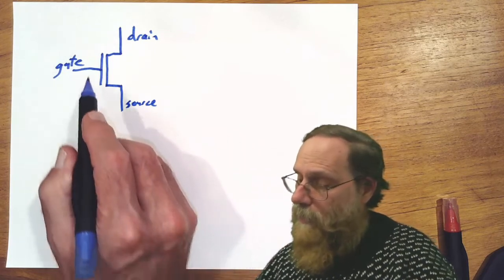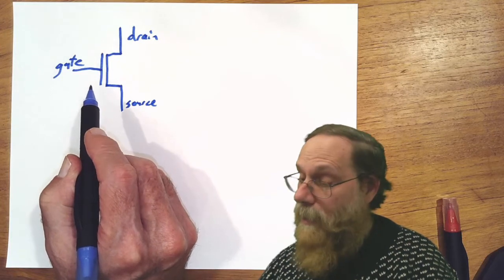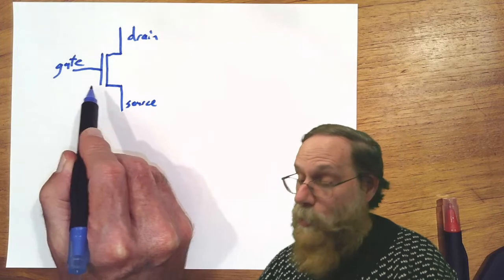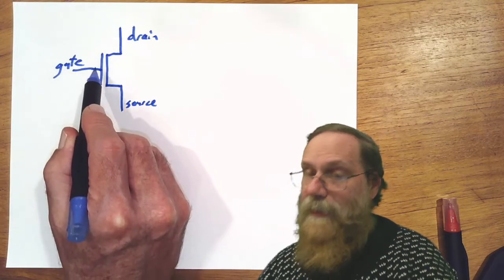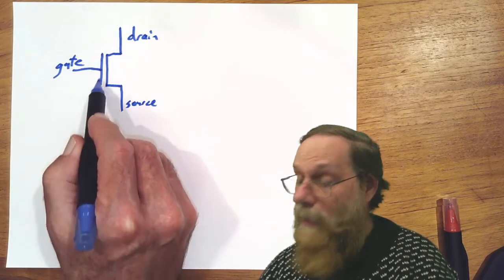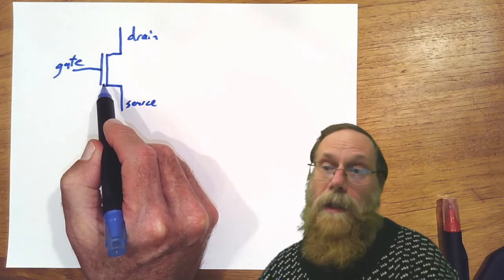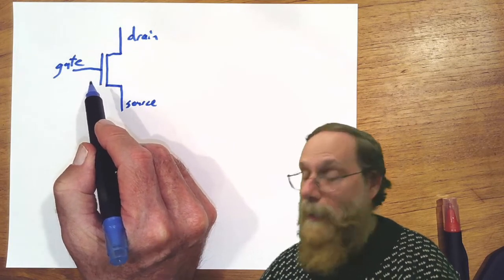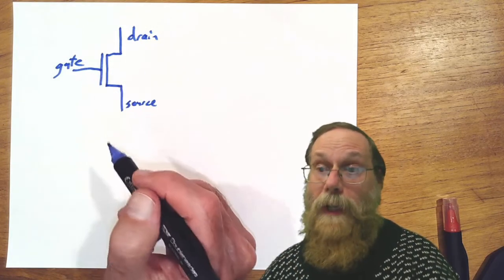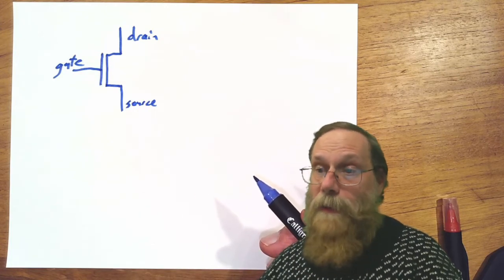because there is an oxide, generally silicon dioxide, sometimes a little bit of silicon nitride as well, an insulator layer there between two conductors. One conductor, traditionally metal, but often now polycrystalline silicon, is the gate electrode, and the other conductor on this side is the channel that connects the drain and the source, so that we have effectively a capacitor.